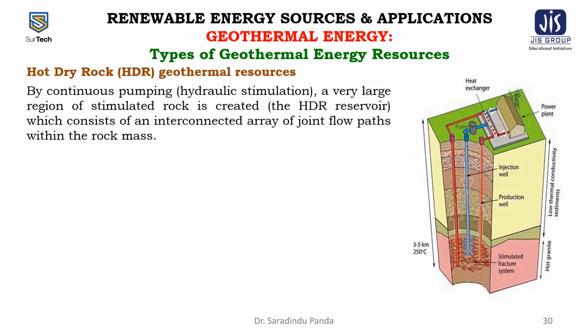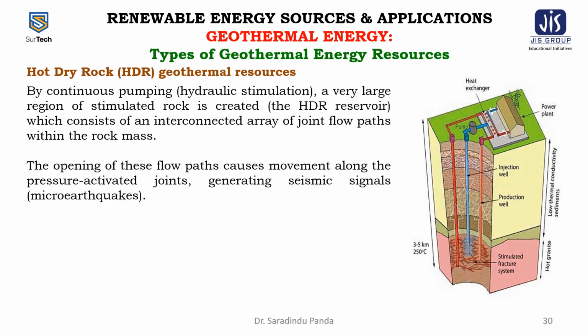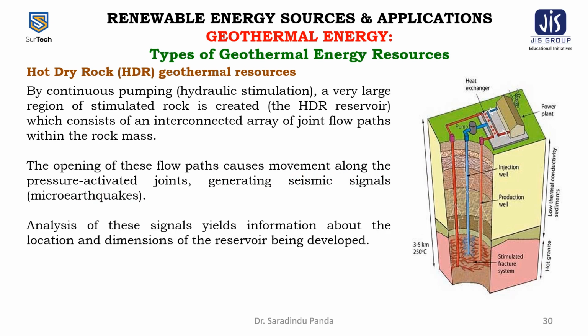By continuous pumping, a very large region of stimulated rock is created, which consists of an interconnected array of the joint flow paths within the rock mass. The opening of these flow paths causes the movement along the pressure activated joints, generating the seismic signals that are called the micro earthquakes. Analysis of these signals yields information about the location and dimensions of the reservoir being developed.